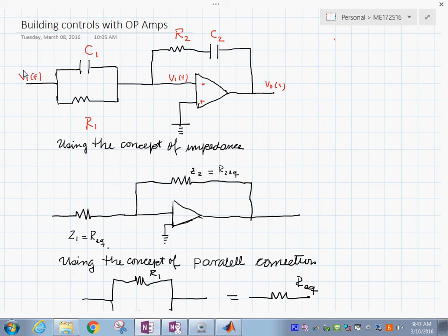So we need to reduce this whole entire circuit to some factor that relates the output voltage to the input voltage, and obviously that relation is the so-called transfer function. What we saw in the last lecture and previous video is that this section of the circuit can be reduced to its impedance, like here. And these two elements in here can also be reduced to their impedance here, some equivalent, as if they would be just two resistors.